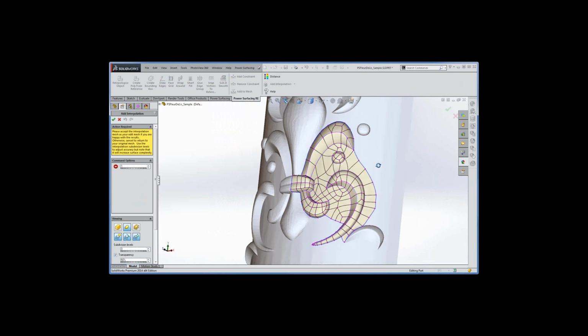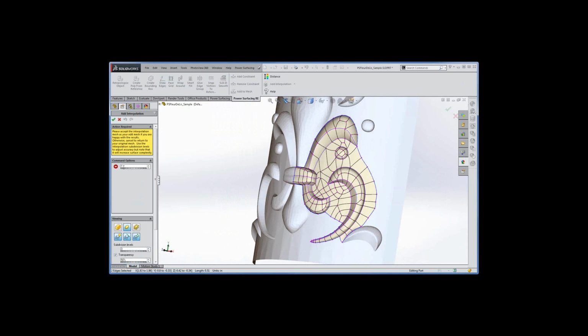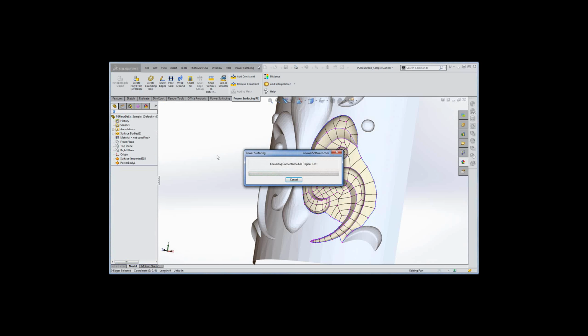you see something like that, and I'm just going to convert it with one subdivision here. We'll say OK, and convert. And it'll come in with some crease on there. Once you've got a crease in there on the SolidWorks side, you can go ahead and add fillets or whatever to get the right amount of curvature you want on it.